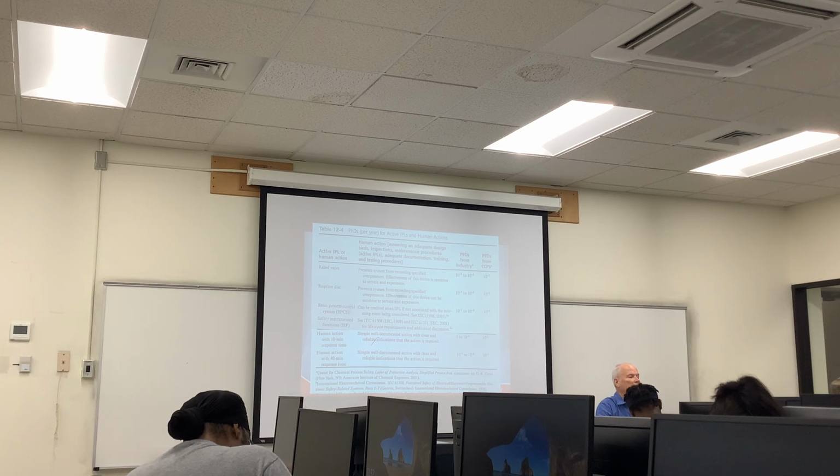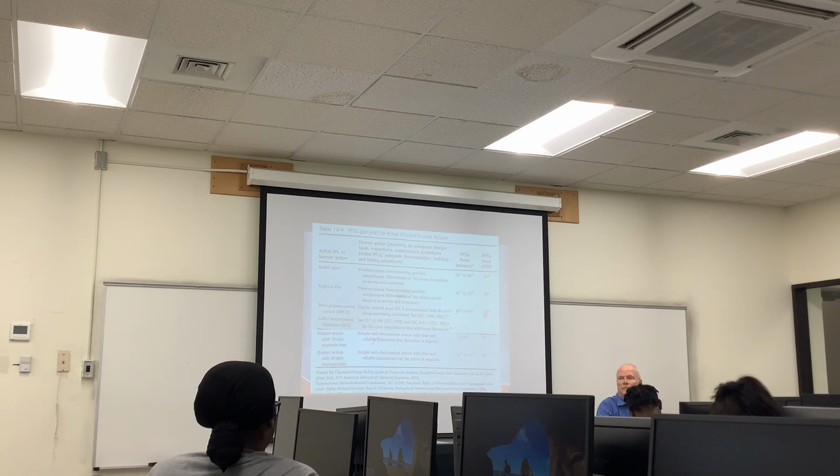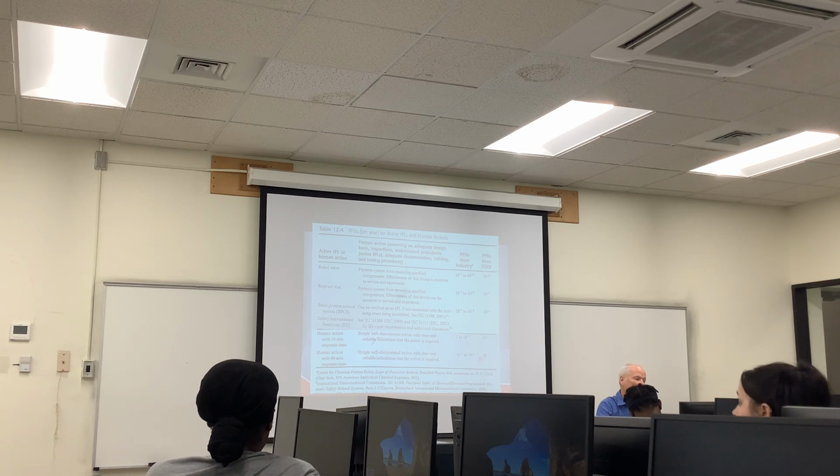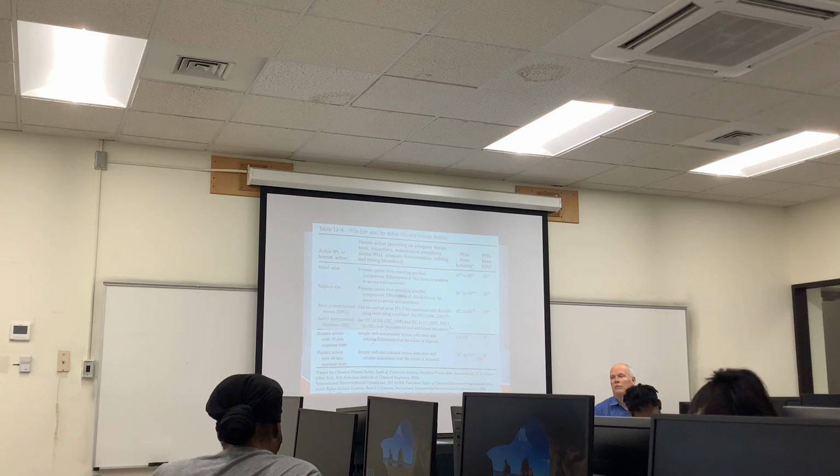What's the probability of failure on demand of the basic process control system? 10 to the minus 1. How about human action within 10 minutes? 10 to the minus 1. Human action within 40 minutes? 10 to the minus 1. Okay, so these are all IPLs that we can take credit for, potentially. I mean, if you have them, right?